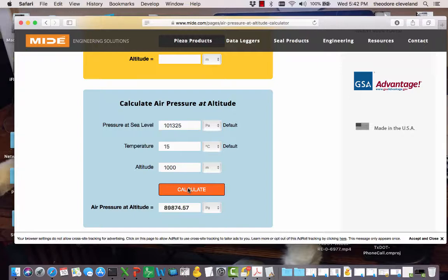We're going to divide that by the value of specific weight of water at 25 degrees Celsius, which is 9781 newtons per meter cubed. That we got from an online tool. We'll go look at that real quick.